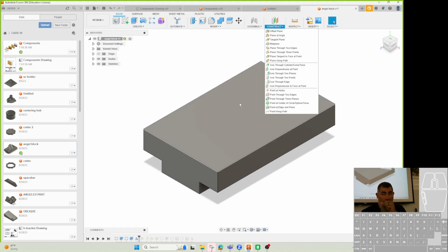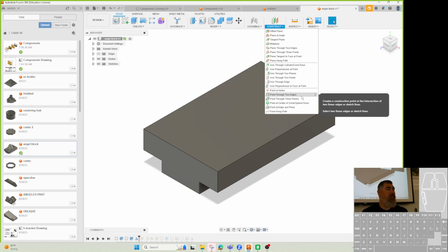So I need to create something there. I can either come out here and create a sketch line or an axis. We could do a sketch here, draw a line 33 over, and use that. But like I said, I don't like to use sketches if I can use features. Features are features, and I prefer to use those.